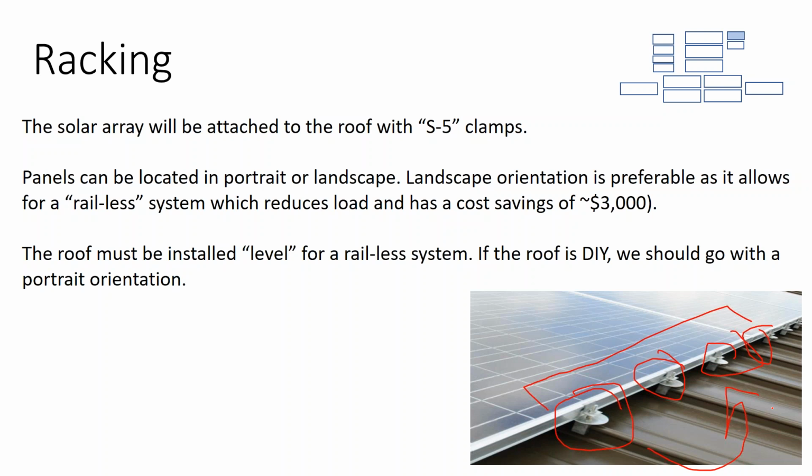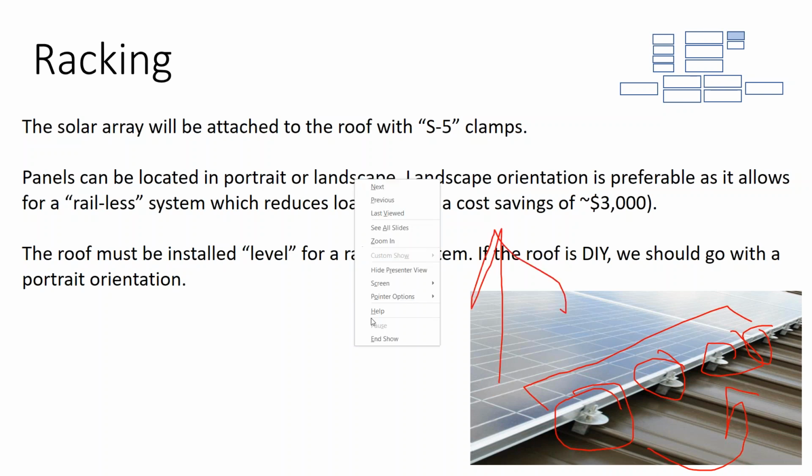And so what would have been really expensive is if on a standing seam metal rooftop, we had put an attachment on every seam and then did the rail on top of that. That would have been unnecessary cost. Structurally, it would have also been unnecessary weight. And on a standing seam metal roof in particular, that extra weight, when you get uplift force from a 3-second wind burst, is going to put even more force on that metal roofing panel.